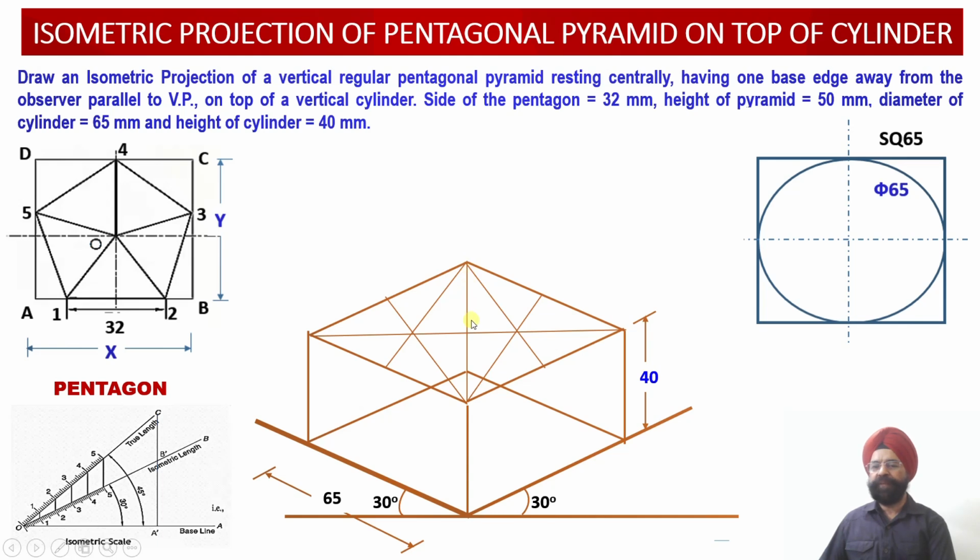To begin with, we are going to obtain the midpoint of all four edges of the top face of this particular square construction. So this is a square construction. For all the edges, we have evaluated the midpoints of all four edges over there. Then corresponding to this minor diagonal of the upper square, from one corner I will be drawing two projector lines which will be joining the midpoints of the opposite edges of the square.